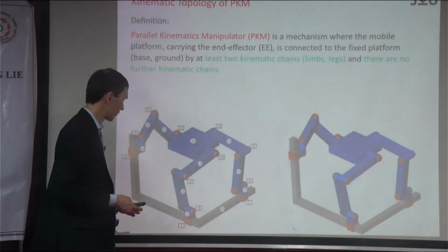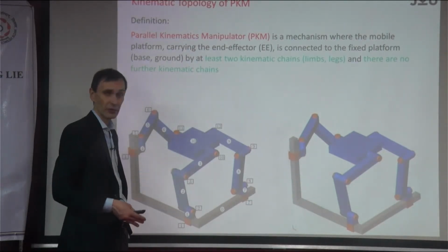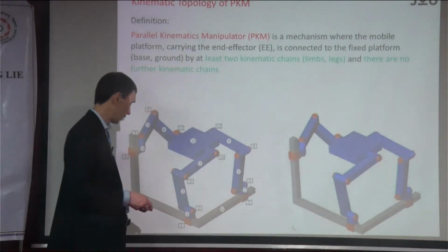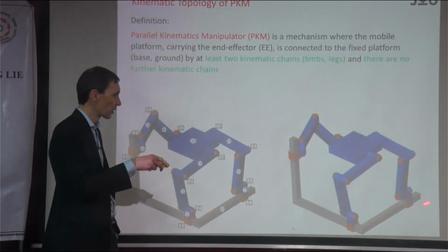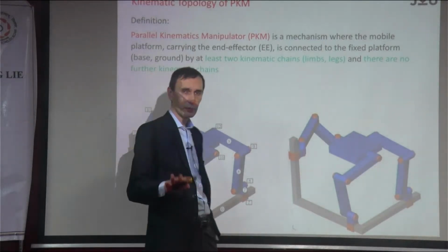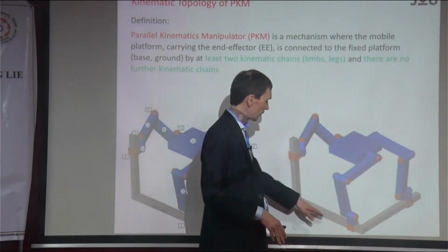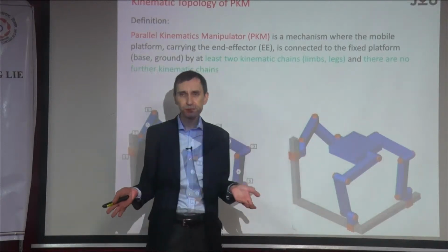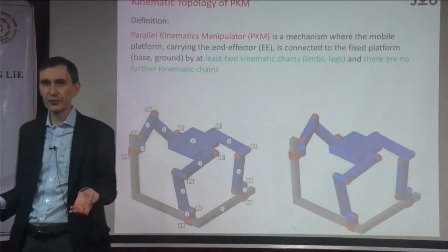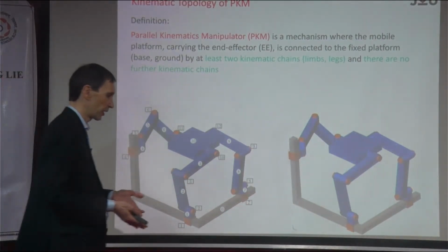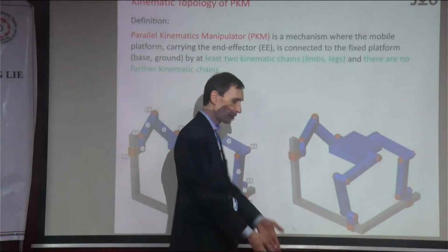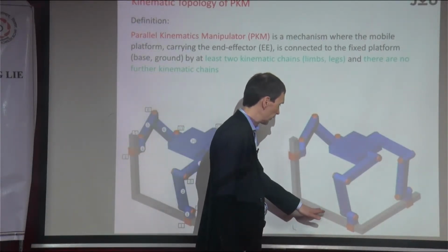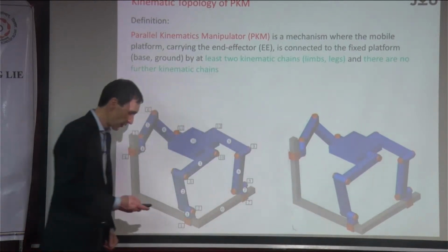First of all, why do we number the bodies or the links, right? I would start with the ground, because we are talking about a stationary system. The ground I always give the number 0, right? We number the bodies, and there's one body I'm not interested in, but I have to somehow number it, which is the ground, because the ground's not moving. I don't care, for the time being at least. And this gives number 0.